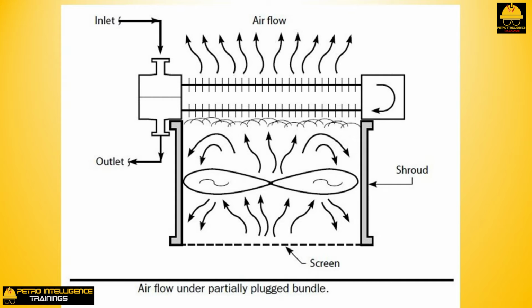Cooler weather always increases the airflow produced by a fan. This always increases the amp load on the fan's motor driver. To prevent the motor from tripping off, or simply to save electricity during the winter, you might reduce the fan blade pitch. One factor that does not reduce airflow is crushed fins at the top of the tube bundle.